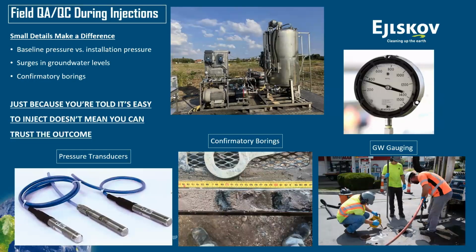When we look at the monitoring part during the injection, some of the little things that we look at, and it's not so small, but they are important. One is definitely the pressure. Just when we inject, I think that's our baseline value that tells us how things are going. So again, if we know that a site is mostly clay based, and I see my pressure not really doing that little break curve that we have seen in the graph before, it kind of starts to raise a question.